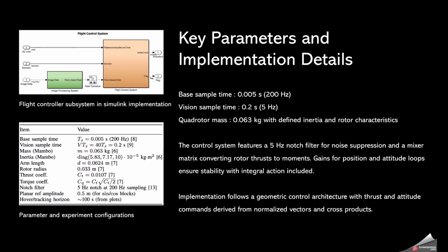The base loop runs at 200 Hz with a 5 millisecond sample time, and vision updates run at 5 Hz. The model uses a 63-gram quadrotor that includes a 5 Hz notch filter and a mixer matrix to convert rotor thrust into moments.